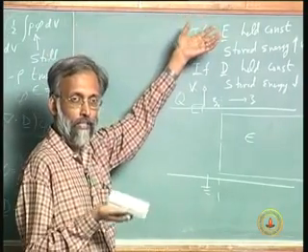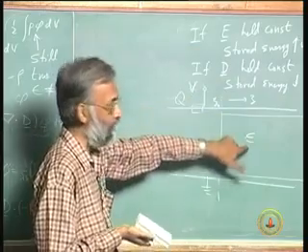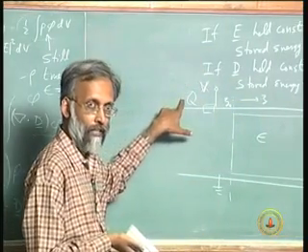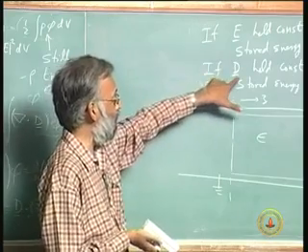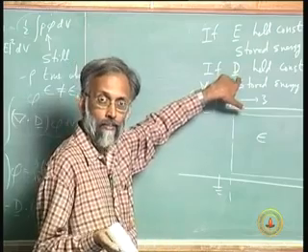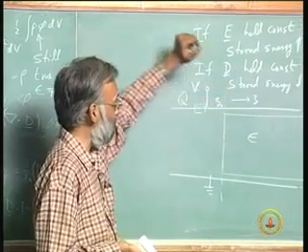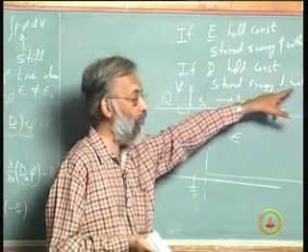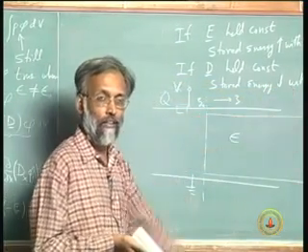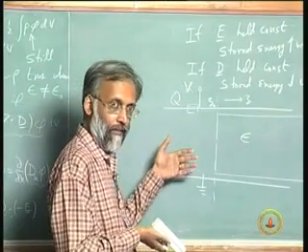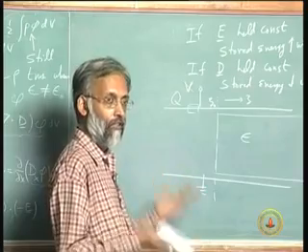Epsilon E squared over 2 describes the stored energy. So, if epsilon increases, stored energy increases. If on the other hand I have stored charge, charge directly talks about displacement vector, it does not care about dielectric constant, and displacement vector is held constant, then stored energy drops with epsilon, and that tells me that if I push it in, the amount of stored energy is dropping.